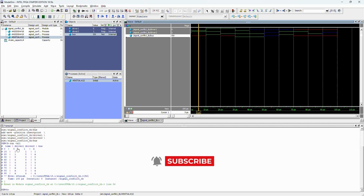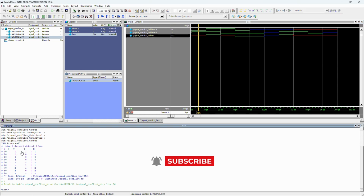If you are driving the same values like 1, 1 and 0, 0, the output value will be the same, 1 and 0. If you are driving conflicting values like 0, 1 and 1, 0, the output will be unknown because both have the same strength, so it gives the unknown value.